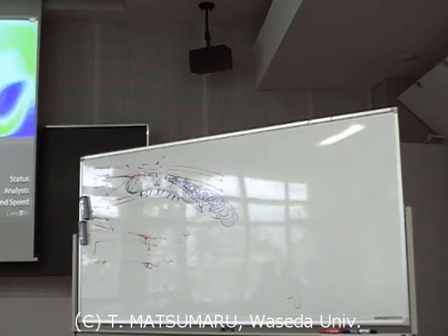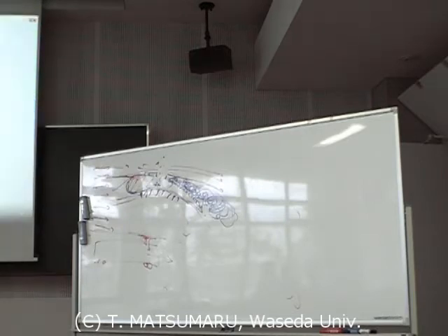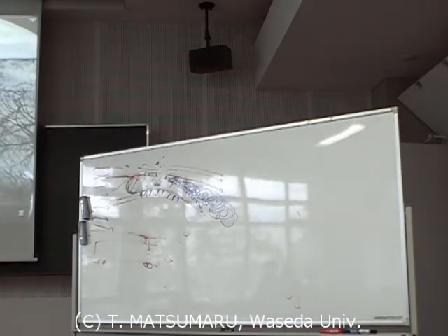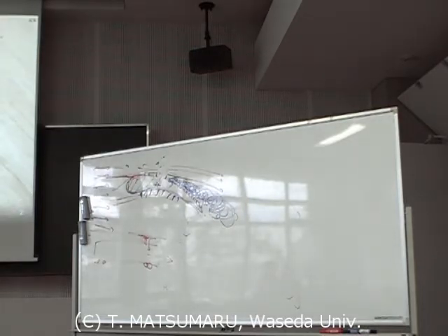I noticed that the raindrops on my car's rear windshield wouldn't get blown off when I would go down the freeway, indicating that the air has separated and was not attached. So I thought it'd be a cool idea to try and 3D print some vortex generators and then put them on my car's rear windshield and see if they would help delay airflow separation. Here is my test.